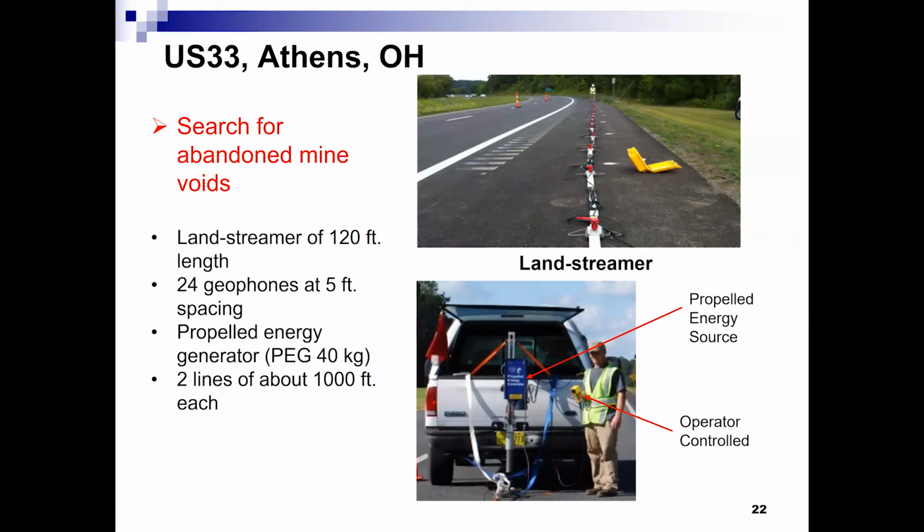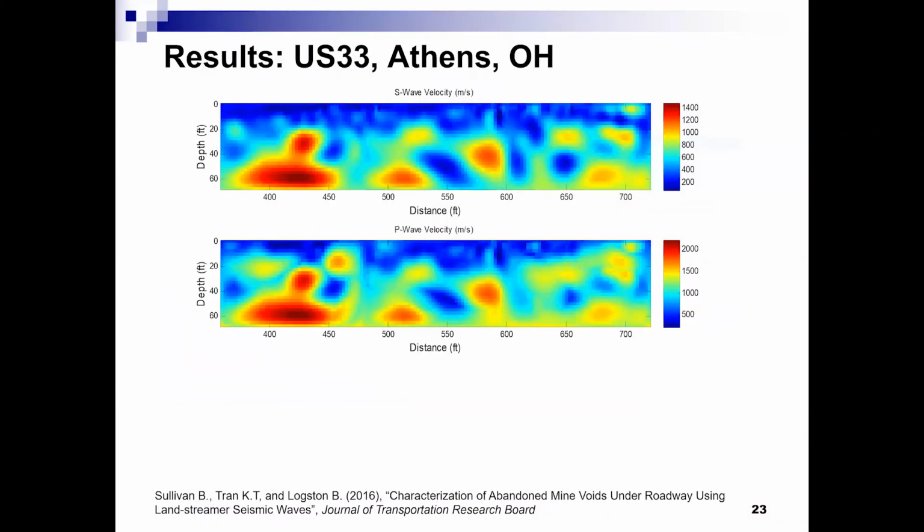Using a motor here, press the button, and this one goes up and down. We can select different heights of the rope, so we can apply different energy if we want. We can also change the impact plate a little bit to play with the frequency content. What is the predominant frequency range? We only use from 5 to 50 hertz.